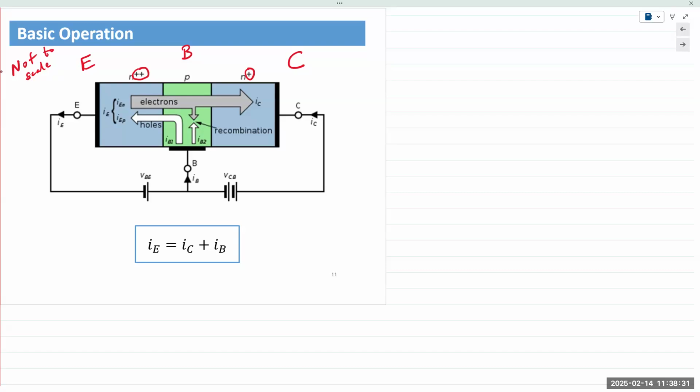How large? We don't know. It simply indicates it's higher, that's all. So it says here, P-type material must have some doping concentration, then it's N+ in the collector. That means the doping concentration is higher than the base, and the plus indicates it's the highest. It's just subjective, it's relative, that's all it is.